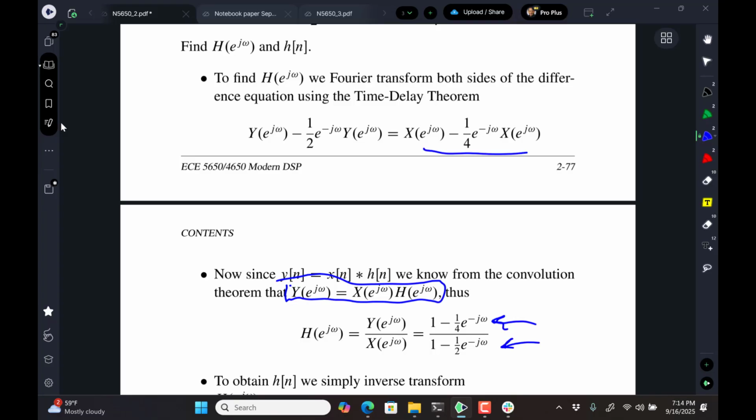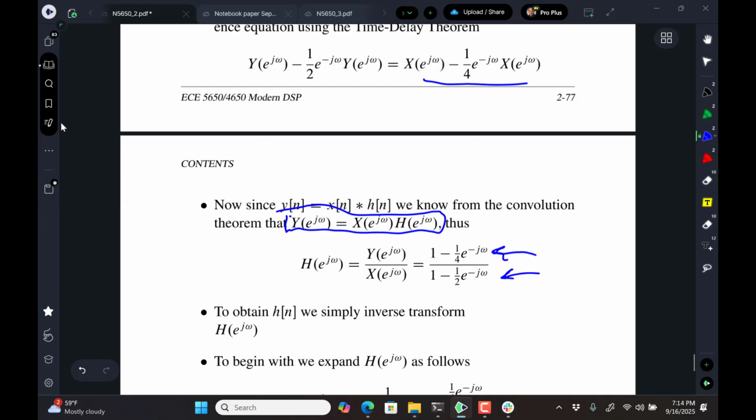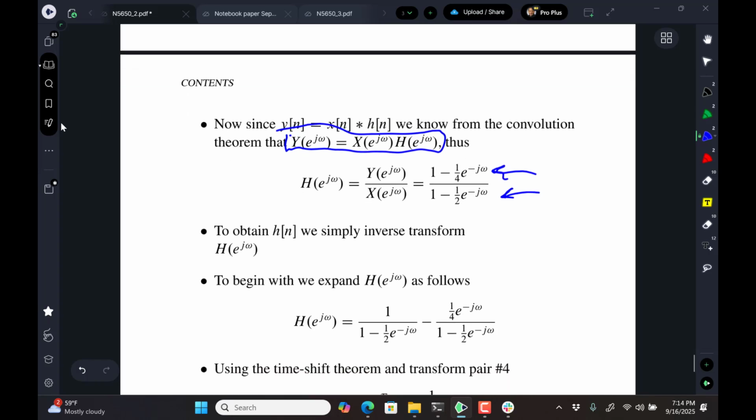And this right away shows you how freqz was set up to work, because it had a numerator and denominator, and it was assuming you had a general difference equation that you were going after to get its frequency response. Does that make sense? How that comes together. This is beautiful. It's easy, easy, easy. You just have to know how to put it together and get it to work.